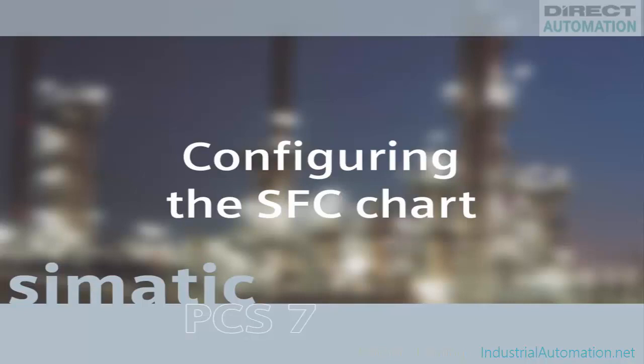In our example, there are two identical process areas or units in the plant. Automation of both of the units must be carried out in such a manner that one unit is fully engineered first and tested prior to beginning configuration of the second unit. The automation programs of the first unit are then copied and adapted to the second unit. Before the CFC charts are interconnected, an SFC chart must be created to control the sequential operation of the motor and valve, since this configuration logic must also be available for the second plant section.